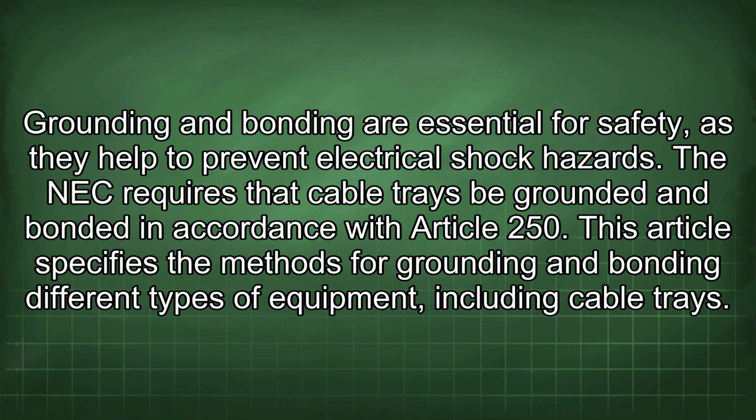Grounding and bonding are essential for safety, as they help to prevent electrical shock hazards. The NEC requires that cable trays be grounded and bonded in accordance with Article 250. This article specifies the methods for grounding and bonding different types of equipment, including cable trays.